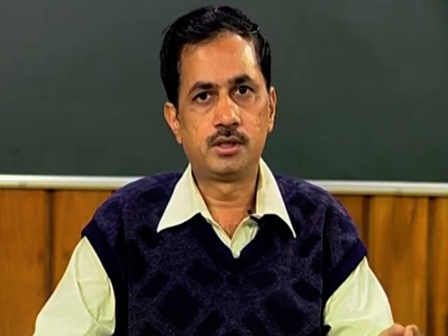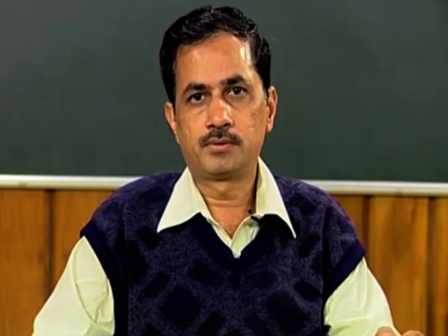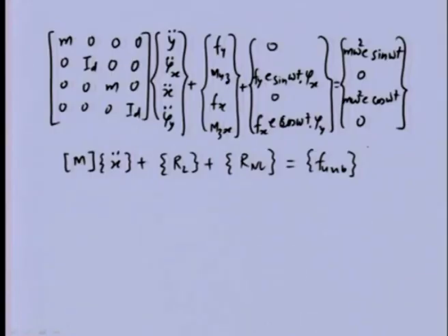Now, we will relate the elastic force and moment which is coming from the shaft onto the disc to the linear and angular displacement with the help of influence coefficients. So, let us see this particular relation we generally study in strength of materials: once we have the displacement, we can write it in terms of the influence coefficient multiplied by the force in that particular plane and the moment in that particular plane.